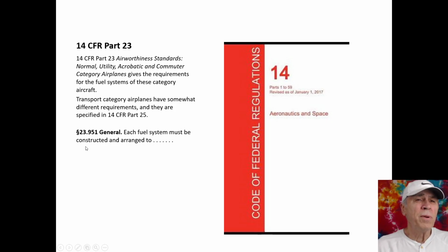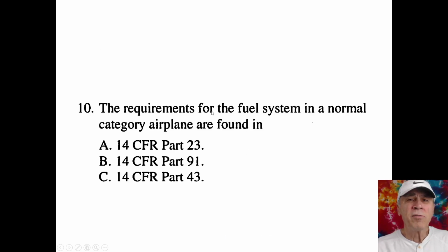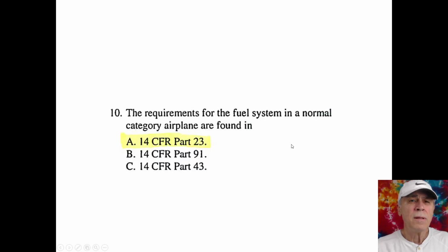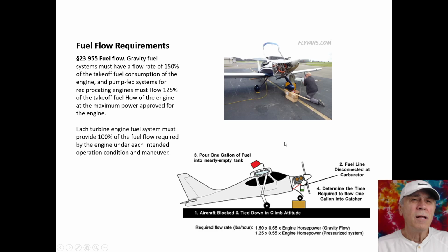Each fuel system must be constructed and arranged to do a number of things. So the requirements of the fuel system in a normal category aircraft is found in 14 CFR part 23. The fuel flow requirements, we already saw that if it's gravity fed, the fuel flow must be 150% of the takeoff fuel consumption. There's also a similar requirement for pump fed systems.